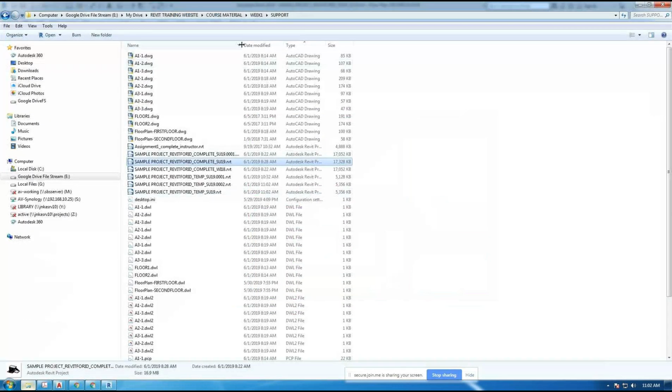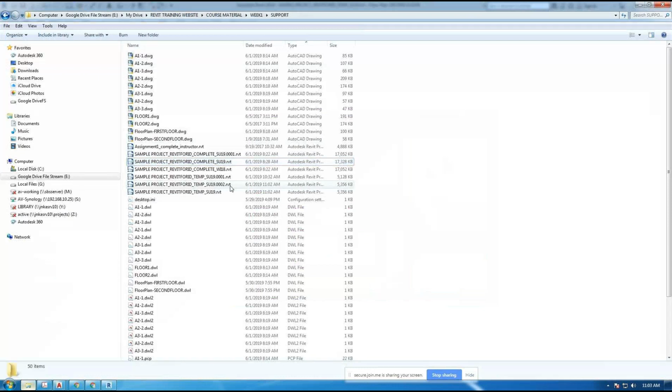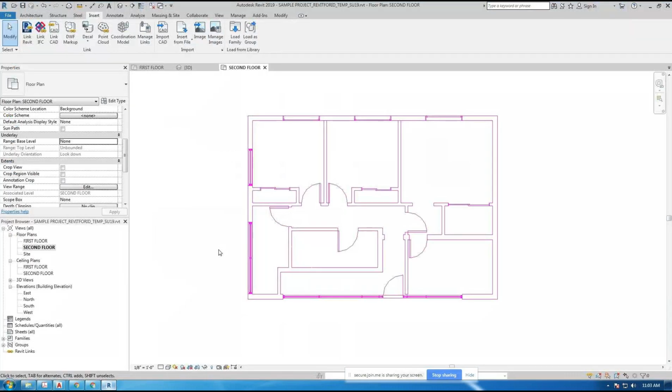Here's my project folder. And let me see. Here are my backups, 0001 and 0002. Those are my backups. So if my project ever failed, I could open that file, number 1 or number 2 or number 3, and bring back this project to life. Revit is complicated enough to crash every now and again. Your files might get corrupted. The only chance you have of recovering your work is to go back to your backups. So save early, save often. Have backups. Don't lose your work.